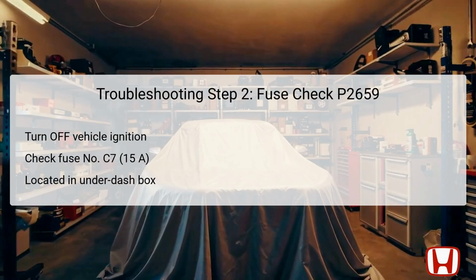The next step in the troubleshooting process involves checking the fuse associated with the rocker arm oil control solenoid circuit, specifically fuse number C7 rated at 15 amps. To do this, the vehicle should first be turned off or to the lock mode. This ensures safety and prevents any electrical malfunctions during the inspection. The C7 fuse is located in the under-dash fuse/relay box, making it accessible for examination. If the fuse appears intact, the troubleshooting can proceed to the next step. However, if it is blown, replacing it is essential.